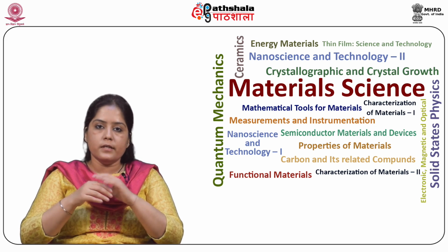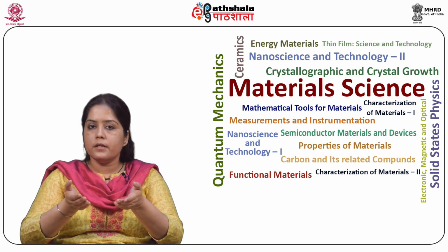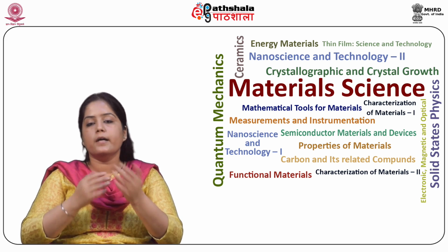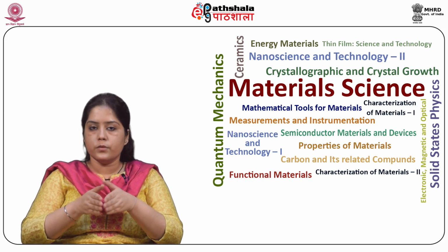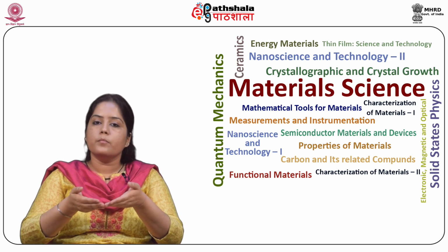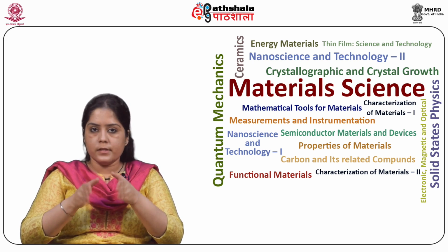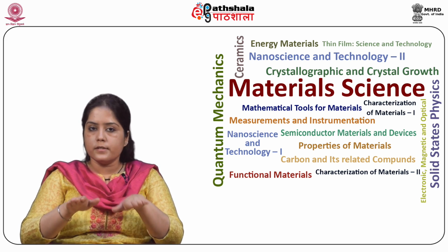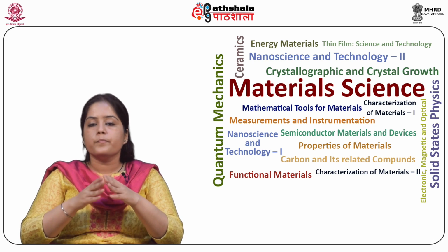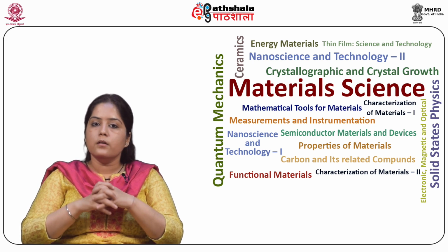Typical electrode materials used in RFBs are based on carbon materials or inert metallic materials. Carbon-based electrodes are more common compared to the metallic materials since carbon materials do not undergo dissolution or the formation of oxide during chemical oxidation.